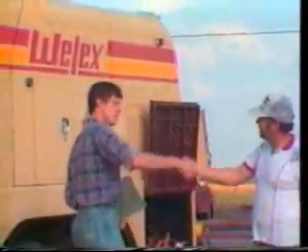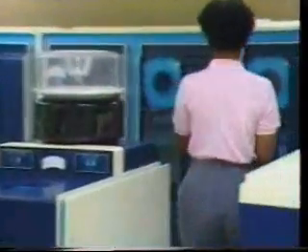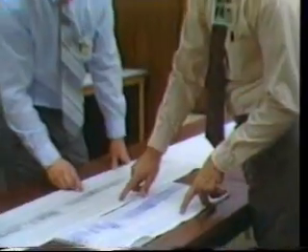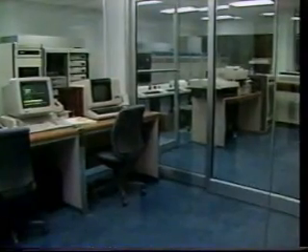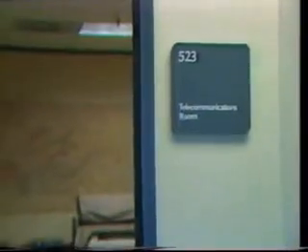The logging survey doesn't end when the logging unit leaves the well site. Activity may move to a log evaluation center, where final prints, and in many cases, second-generation logs, additional downhole evaluations, and graphic summaries are made by the logging company in its log evaluation facilities. If requested, final results from these evaluations can often be transmitted to the oil company office in less than 24 hours. Routine processing, however, can take from 2 to several days.